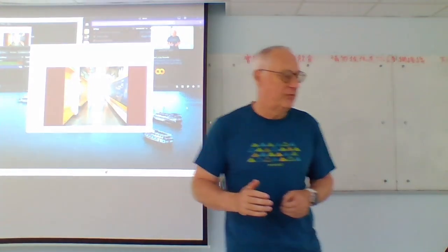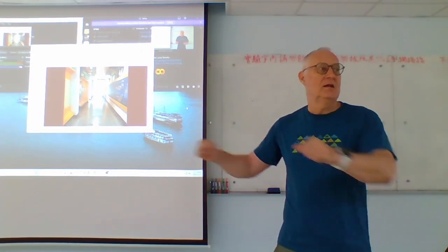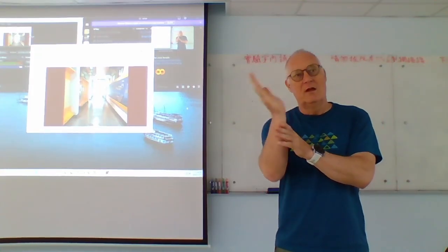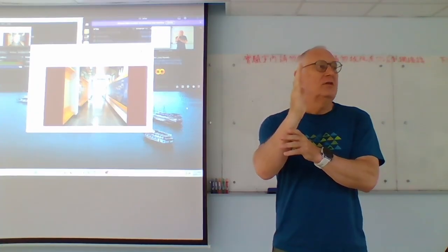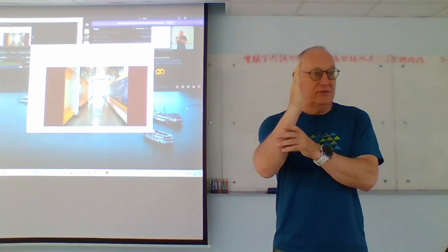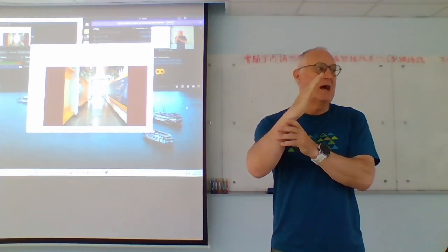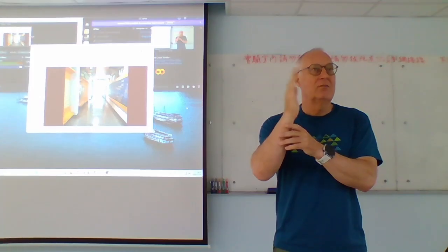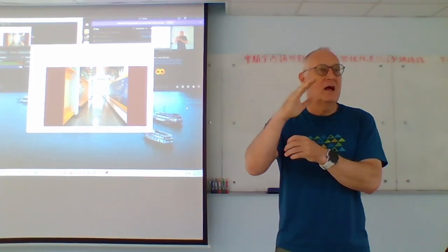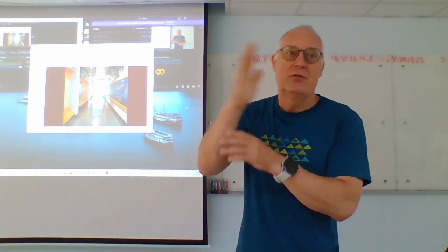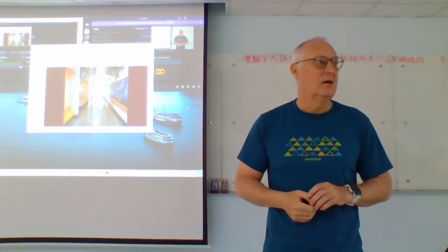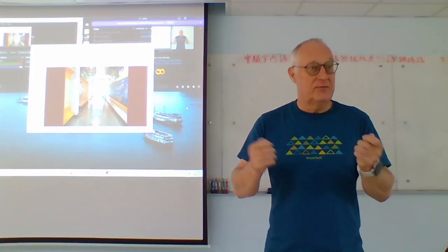So what happens is if you have the robot and you lean it to 10 degrees and then you pull it to 0 degrees, 10 degrees, 0 degrees, so the robot just does this. Then after you do this 20 times, the robot would be at 0 degrees looking straight up. But in fact, not your sensor, but your algorithm, the noise will have added up. So you'll be saying that you lean 5 degrees to the left or 5 degrees to the right or something like that. So that's a huge problem, this drift error in gyroscopes.